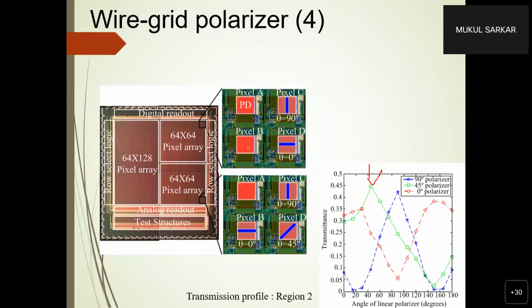The second question: sir, I agree that processing means power consumption. Can we fix the resolution, whatever is required for the measurement, and then restrict the power here? Yes. Many large format imaging sensors give you an option to work in ROI based readout mode, right?